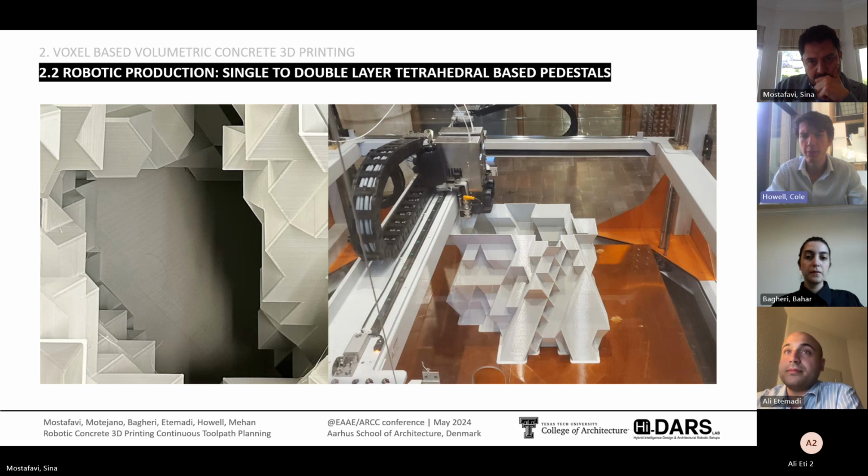To prototype the proposed concrete forms and to have a backup in case of failure during transit, we printed two of the pedestals in-house using a BigRep ONE and PLA. The PLA pedestals helped inform us of design considerations as we move forward. The prototype was 1-to-1 with the concrete version, consisted of a single toolpath, and was a shell lacking an infill.